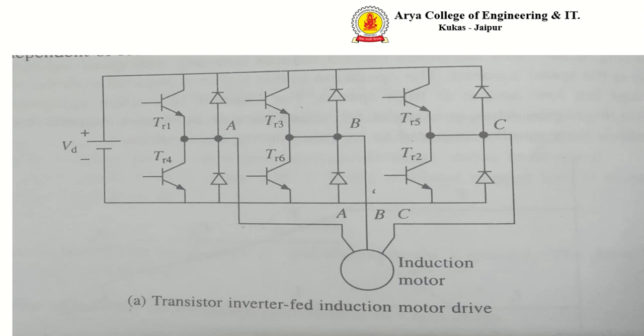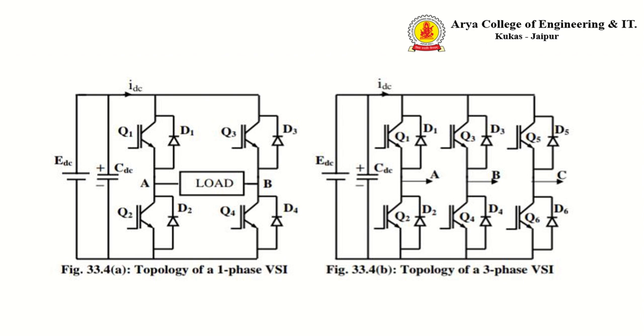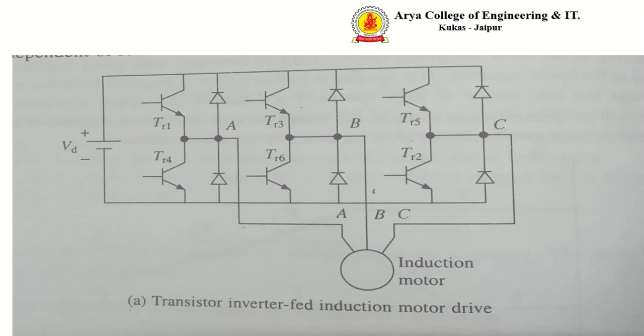When these configurations are used, some drawbacks occur in voltage source inverter control of the induction motor drive. First drawback: because of the low frequency harmonics, the motor losses increase at all speeds, causing derating of the motor. Second drawback: the motor develops a fluctuating torque due to the 5th, 7th, 11th and 13th harmonics.